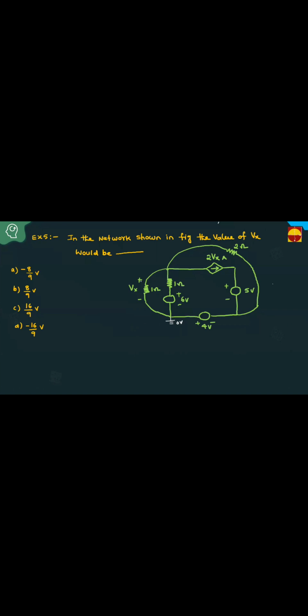This is Vx. Vx minus 0 is Vx. That's why it is Vx, because it is a reference node. The reference node potential is equal to 0 volts, then Vx minus 0 equal to Vx. Now apply the nodal analysis, students. You have to find Vx now.